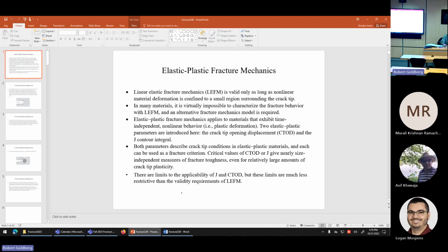Overall, the scores on the midterm weren't too bad. Probably the biggest thing I noticed, I'll admit, problem three was a bit of a trick. It was the one trick I threw in there. The trick to that one is that you were given the equation for the stress intensity factor for an edge crack, and then you were given the equation to take the stress intensity factor and convert it to the strain energy release rate, which gives you your G equation, and then from there just proceed as the homework progressed.